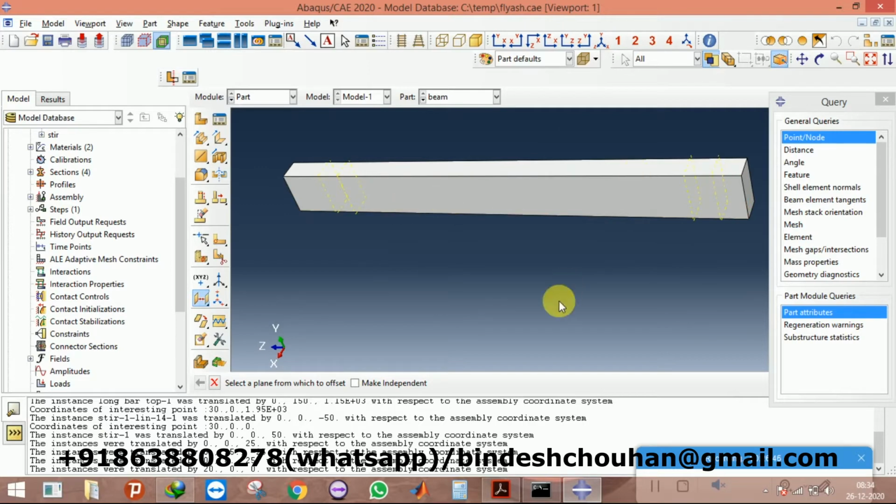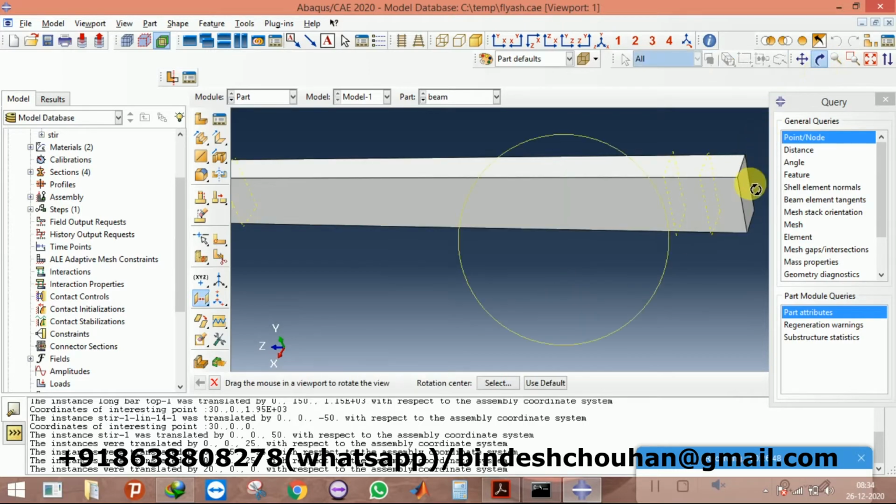This I'm just creating so that I can assign the block over here. And then for the loading block, the spacing is 625 from each side. Loading is applied, so if I minus 625 minus 50, it is 575.